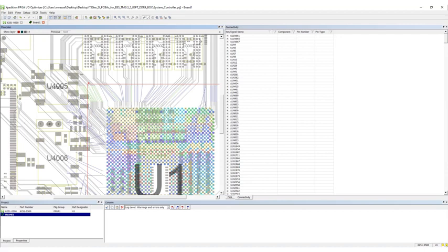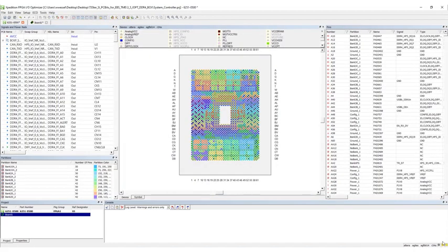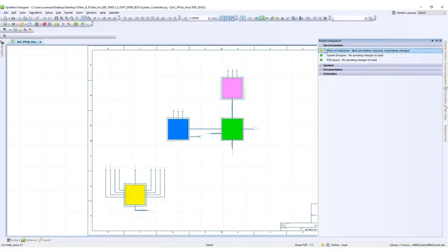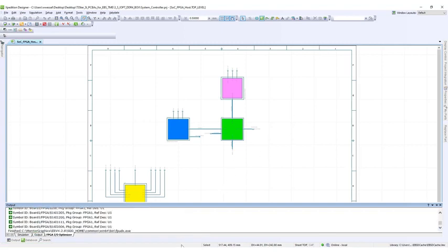The engineering change order process does not only write back data to the PCB domain. It fully supports a bidirectional exchange of native file formats from FPGA vendors like Intel, Xilinx, Lattice, and Microsemi. In our case, we are using a VHDL signal source and a QSF constraint file for the pin location.